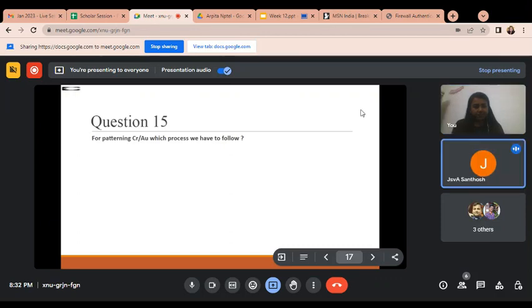Hard bake, ma'am. Yes, hard bake. And what is the temperature and time? 120 degrees Celsius and 1 minute. Yes, ma'am. Okay. So after the development process, hard bake will be done. After hard bake,